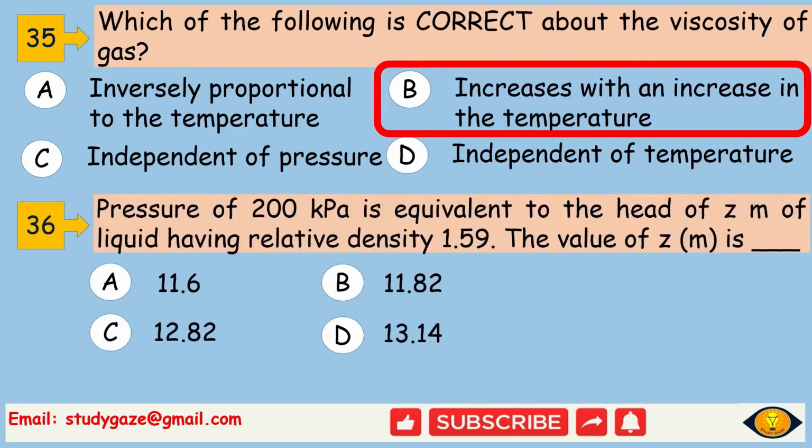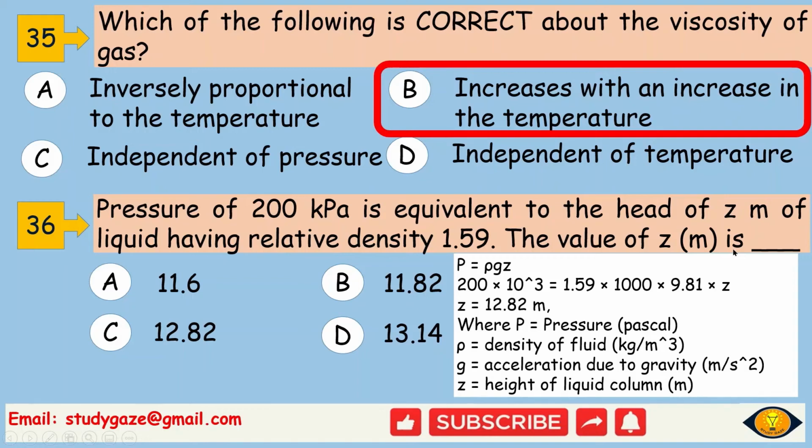Next, a pressure of 1200 kilopascal is equivalent to the head of Z meter of liquid having relative density 1.59. The value of Z in meter is, as we know, P equal to rho g z, and P is given as 1200 kilopascal, so it will be 1200 into 10 to the power 3 equal to 1.59 into 1000 into 9.81 into Z. By using this equation, we will get Z in meter, that is 12.82 meter.